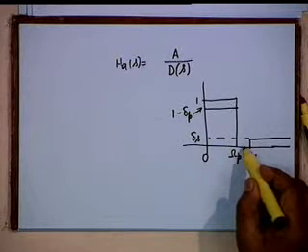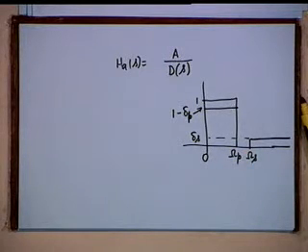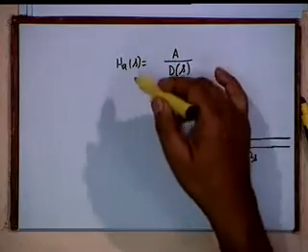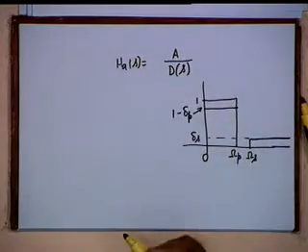Liberties means what? You can over satisfy. For example, if my stop band starts earlier, I am happy. Isn't that right? Because I over satisfy the stop band. So this is what our job is, to determine an H A of S which satisfies these specs.